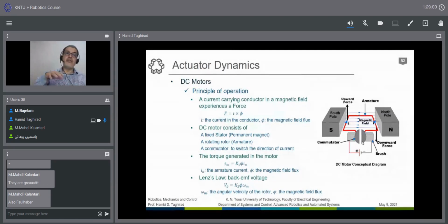As the speed goes high, the back EMF reduces it like a feedback, and you have a balanced angular velocity of the motor. In a usual DC motor, we have about 3,000 RPM to 5,000 RPM. And the torque that we can get from a small motor is about 1/10 of a Newton meter. It's very, very small. The velocity is usually high, and the torques are usually low.